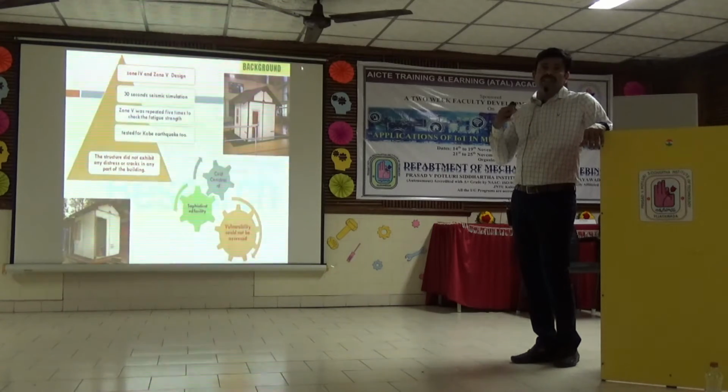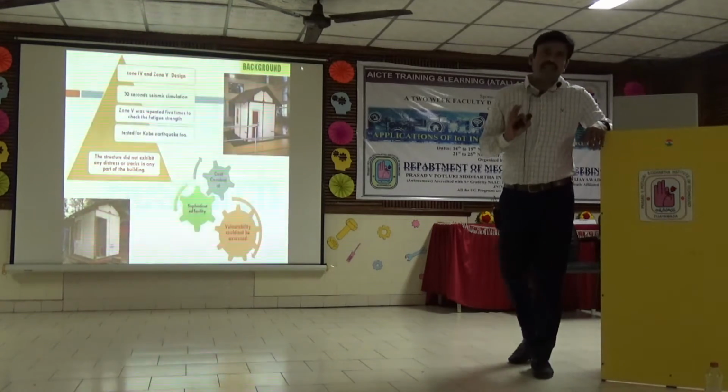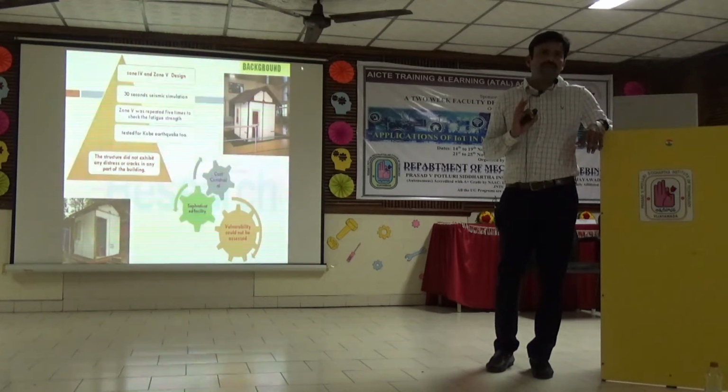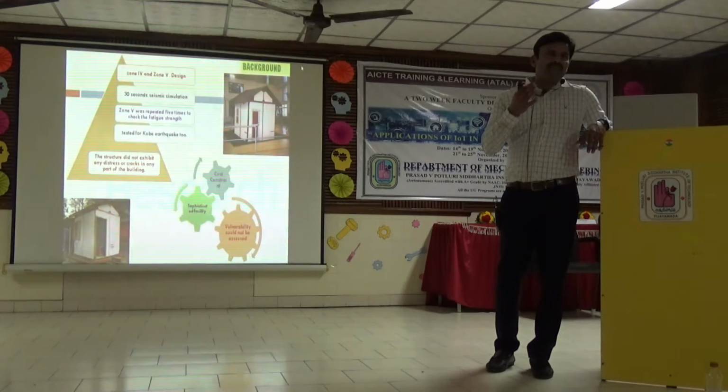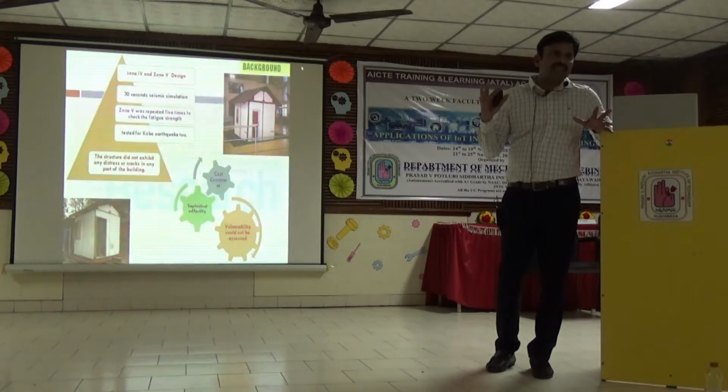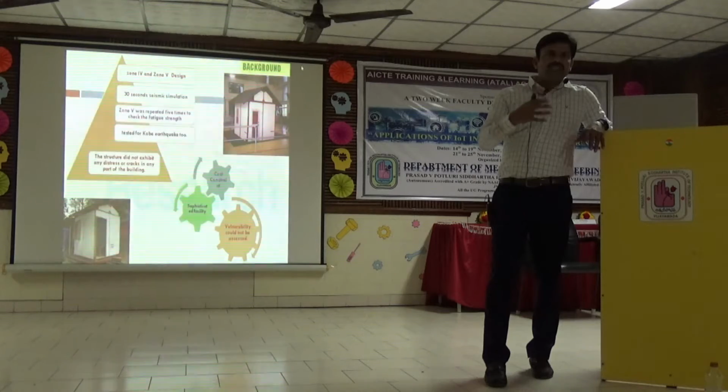I understood that same house was already tested on a shake table, which was at CPRI, Bangalore, Central Power Research Institute, wherein you can test the seismic performance of the building three-dimensionally. But why does Central Power Research Institute have the shake table? That is to test the transformers, because transformers become vulnerable in the event of earthquakes. That's why each and every sample of transformer, they will test it for the earthquake.